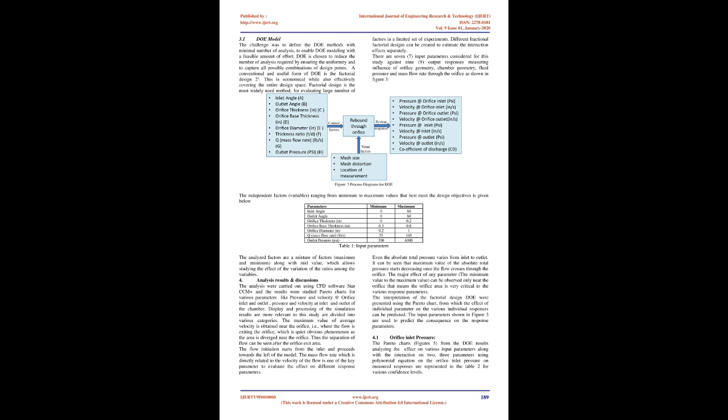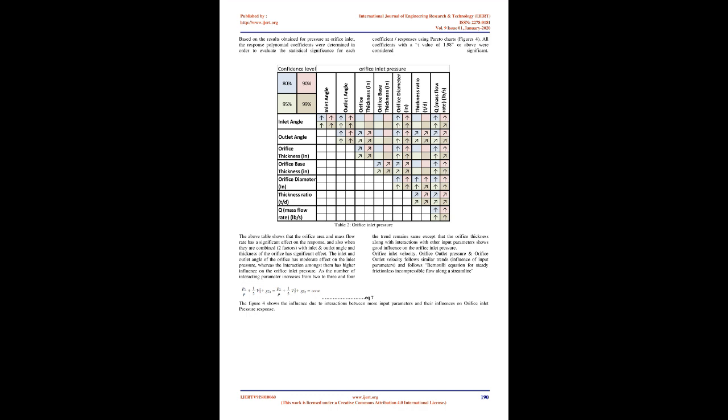Where m_crit is the critical mass flow rate, mu is the dynamic viscosity, SR is the restriction area, Rec is the critical Reynolds number, SA is the nozzle inlet opening, PA is the nozzle inlet pressure, PB is the nozzle outlet pressure, m is the mass flow rate of the system, CD is the coefficient of discharge, rho is the upstream density, and R is the area ratio.